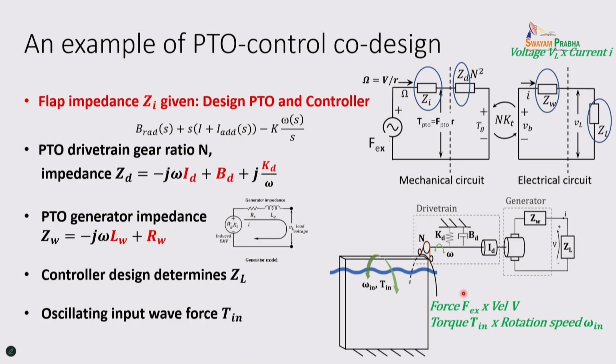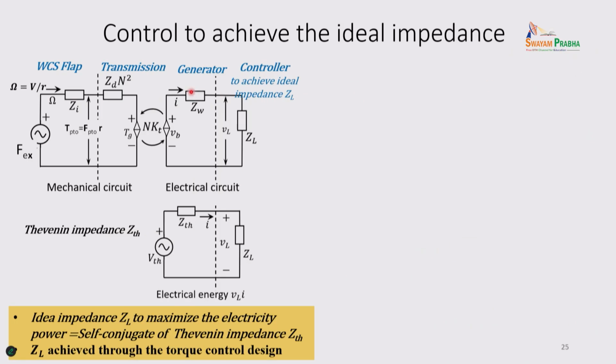However, for this wave energy converter, if you consider the non-ideal case, generators, inductance, and resistance, and PTO system damping, right? And friction, all these types of things. Maximizing the mechanical power is less ideal. You want to maximize the power output. Okay, so that is the PTO control.